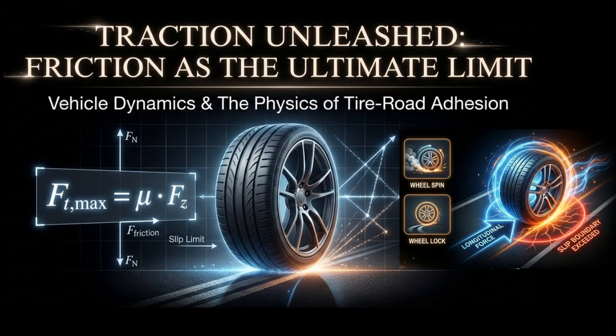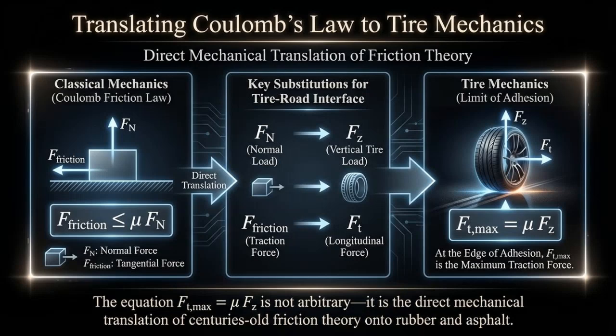Friction also has a maximum limit. If the required force exceeds this limit, the tire can no longer grip the road. The tire then slips, either spinning during acceleration or locking during braking. Understanding this friction limit is essential for vehicle control and safety.